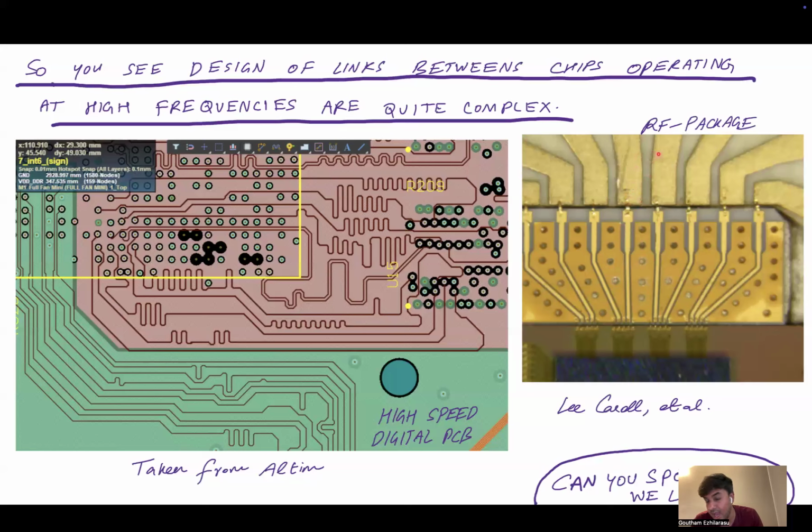So here you see a high frequency 50 gigahertz RF package where you have these adiabatic metal interconnects, which are microstrips. Then there's a high frequency wire bond, which is typically a ribbon type wire bond, that connects to these transmission lines, and these transmission lines are bent adiabatically. Finally, the signal is fanned in, and then there's again a ribbon bond and it is sent all the way to this chip. This is for a much higher frequency application. So you see how, depending on the application and the frequency, the kinds of designs and mitigation strategies you use for signal integrity can be very different.